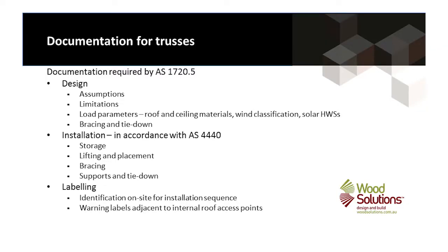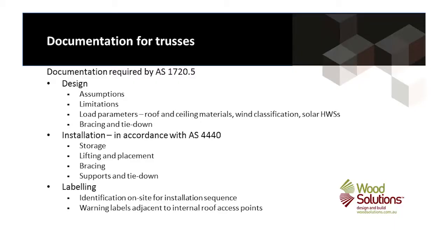And then installation, so that the truss manufacturer will produce specific information on the installation for those trusses. Are all trusses the same? No. Some trusses are girder trusses that have higher loads, and they need to have different installation requirements for them. So the installation requirements include lifting and placing, bracing them, supporting them, and tying them down.